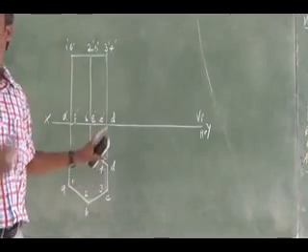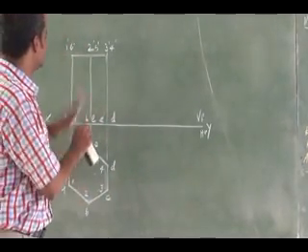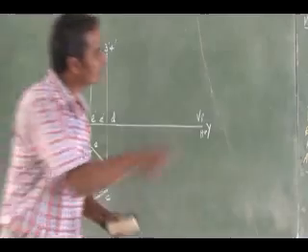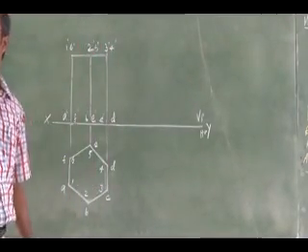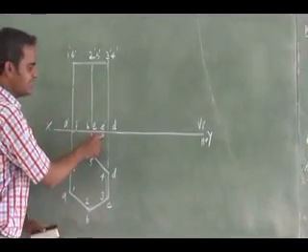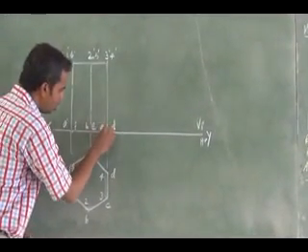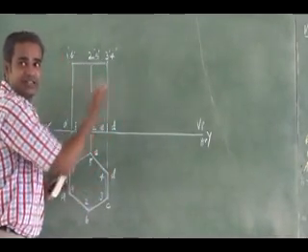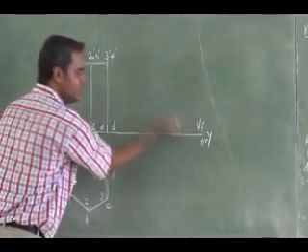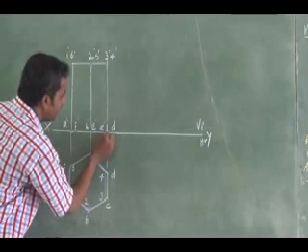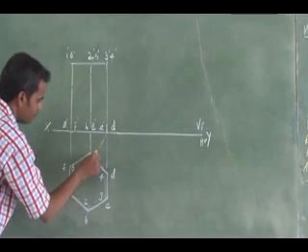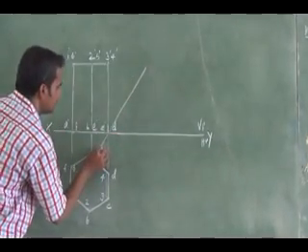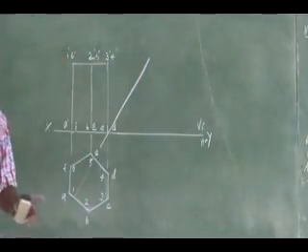In this, I can avoid drawing one view, redrawing this front view. I can keep this as the final front view. Right, what I am going to do is just change the reference line to 30 degree. I know the resting edge is CD. I am just changing the reference line, touching the resting edge CD. The reference line I am tilting, and I am redrawing the reference line here. A new reference line I am drawing.